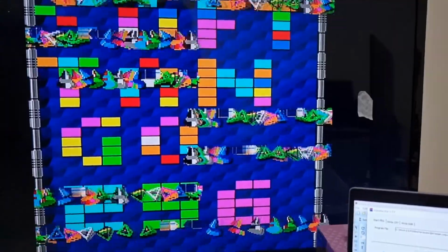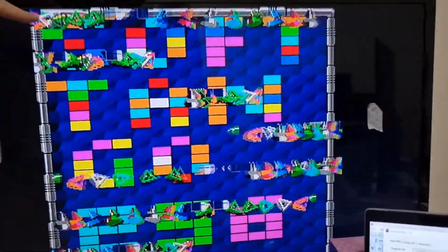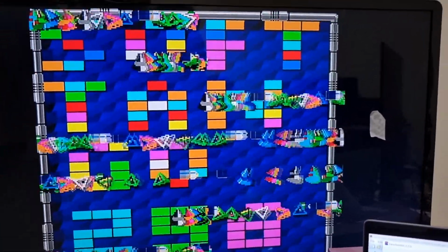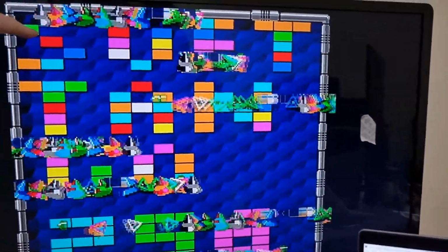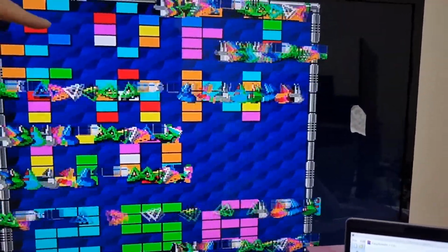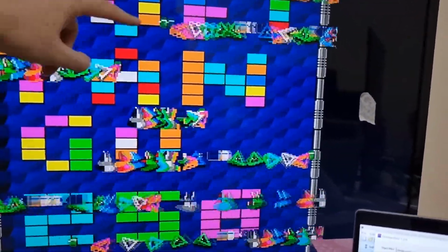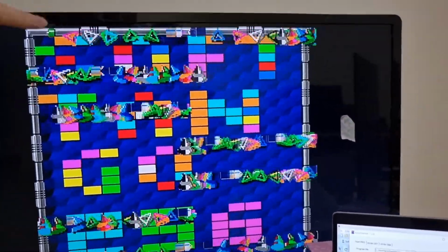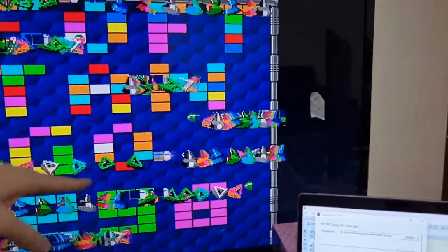So I'm using the Commodore 64 timer interrupt to count the vertical raster positions as it goes down the screen here, and then what I'm doing is that the CPU, or it could be an interrupt, but I'm using the CPU in this to wait for this line here, and then I'm disabling the sprites and updating their registers and so on and so forth. So basically, sprites update, sprites line update, sprites line update, and I'm going down the screen like this. So actually I'm multiplexing or displaying multiple copies of the sprites as the scan line marches down the screen.